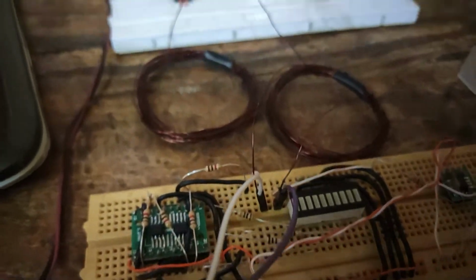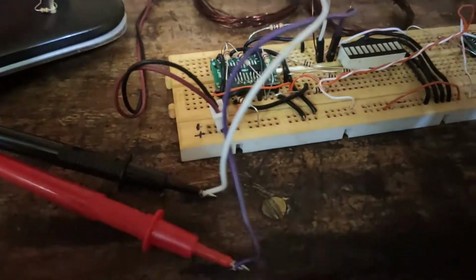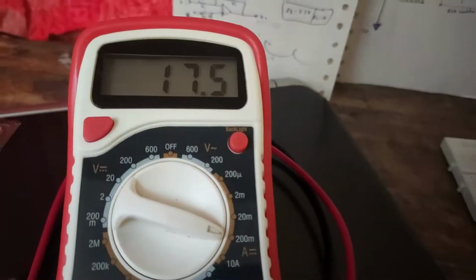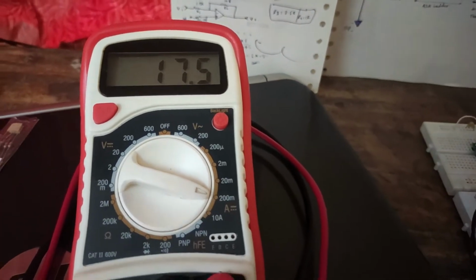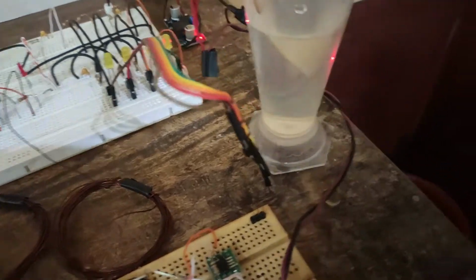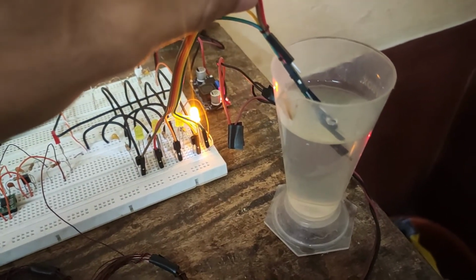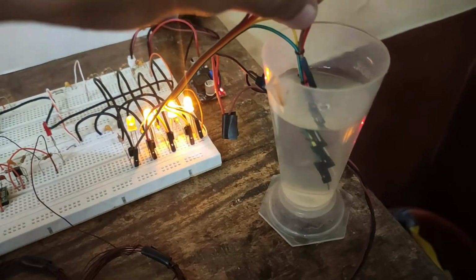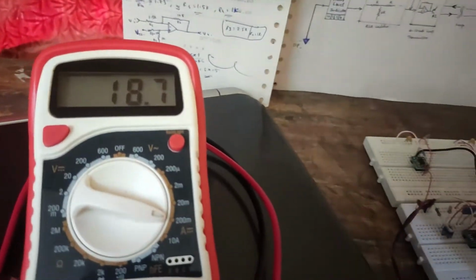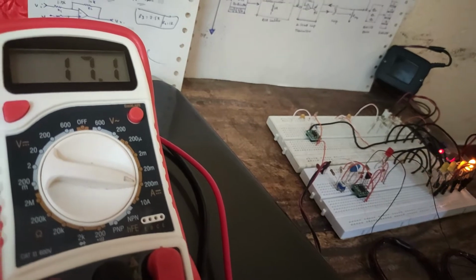So now let's check whether this 4 to 20 milliampere loop is really in that range. I have tied up to the multimeter probe here those 2 points from the current loop, and currently we can see it is reading 17.5 milliampere. That is with nothing. I have not dipped it into the water at all. So now let me put this into the water and interpret if we really get the voltage. This is level 1, 2, 3 and 4. There we go. And let me now see the current. It is 18.8 milliampere now. We'll see it together. I'm lifting this off. The current decreases.